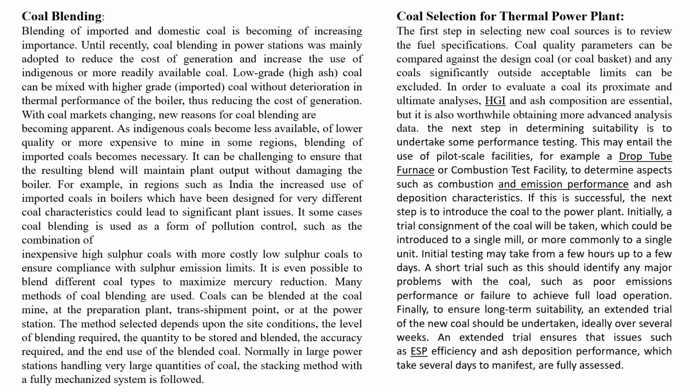So the next step in determining the suitability is to undertake some performance testing at site. This may entail the use of pilot scale facilities. Again, one lab test you have to undergo is the drop tube furnace. It is a furnace where a sample of coal is heated with excess air at high temperature, to determine the combustion efficiency. So you can see the quality of coal in this drop tube furnace test and emission performance test.